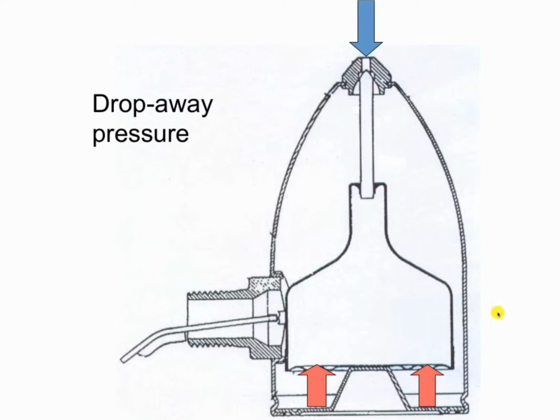What I'm trying to figure out is what level of pressure this building was operating at. And the next thing is, what type of radiators were in these buildings? Were they steel convectors? Were they self-standing cast iron radiators? And if so, what type of air vents were on the radiators? Because that would better help determine what's actually taking place. Like I said before, I've given you a breakdown of this Hoffman air vent, and I've run this on a system that operated at 7.5 to 8 psi. If the radiator's not vented, guess what? The valve is still going to keep venting, even as it reaches 7.5 to 8 psi.